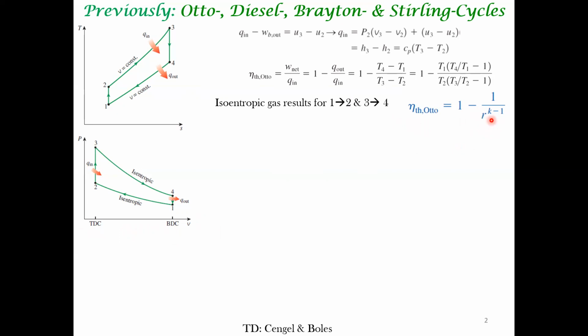Right, so that is the outcome. So how did we arrive at this outcome? Even though there was an open system in reality, that is, there is fuel and air input to the system, and from the outlet, the combusted products are exhausted, you do not really consider such a system. You consider a closed system under the air standard approximation so as to facilitate a simple analysis which gives you efficiency in terms of some crucial feature of the cycle. So that's the approach you take.